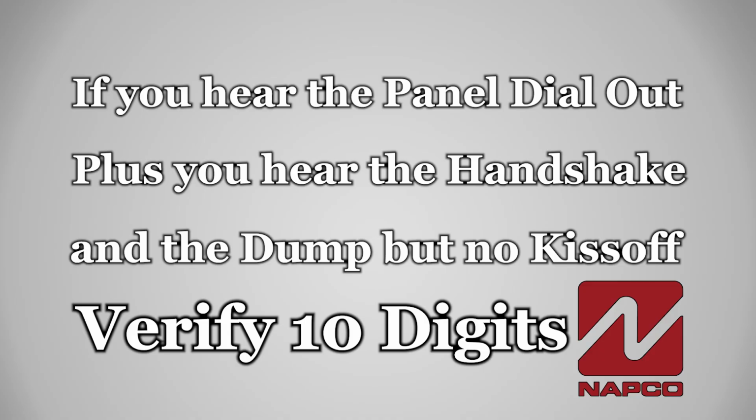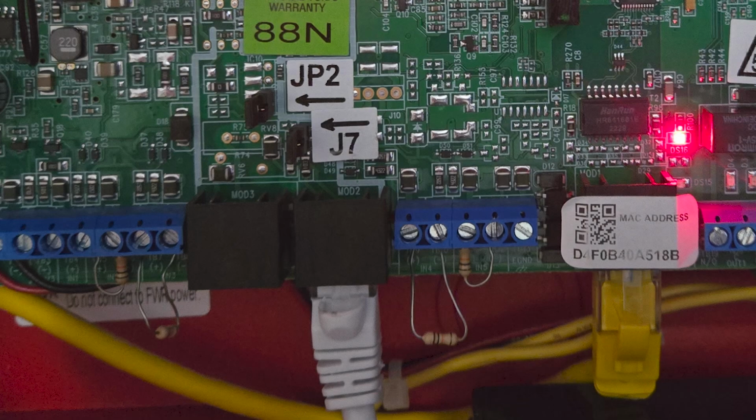If you hear the panel dial out, you hear the handshake, you hear the dump, but you don't hear a kiss off, the first thing to do is check and make sure your panel is dialing at least 10 digits for the phone number. If your panel is not dialing at least 10 digits, you can run into this issue, especially with fire panels. Also, if you have the radio with the 2 phone jacks on it, like this one here, try removing the J7 jumper and try again. For more information on what the J7 jumper does, refer to the manual for your radio.